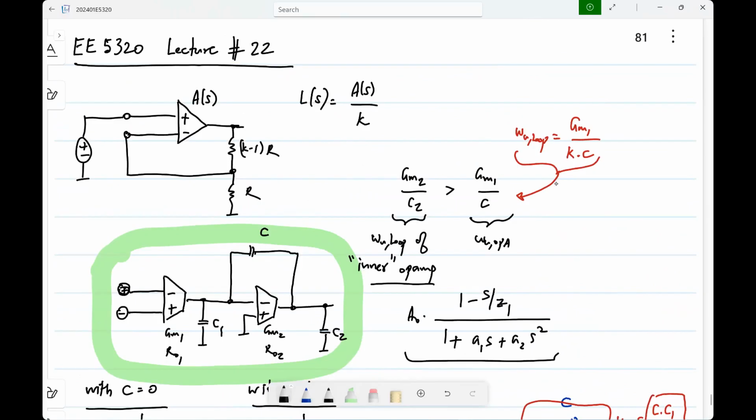What's that? So you assume that when S is substituted by one of the poles, the higher pole, only these two terms are dominant over the other one. And when it is substituted by the lower value, these two are dominant and the other one is not dominant. Okay. So with that, you will get the low frequency pole to be approximately minus 1 by A1. Okay.